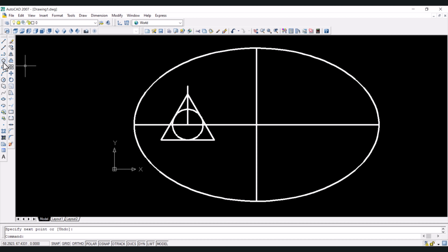So now click on polygon. Now we want to draw an octagon. For that the number of sides should be 8, enter. Click on this center point, click on inscribe now because the distance given is vertex to vertex. So click on the end point of this line, and that octagon has been formed. Click on the line and remove that by pressing delete.